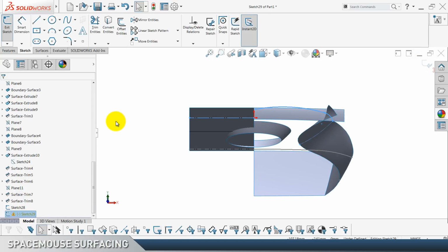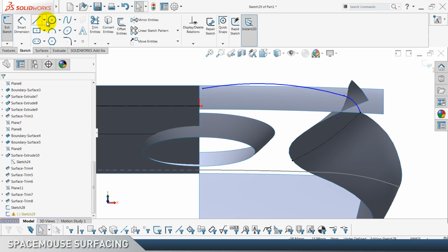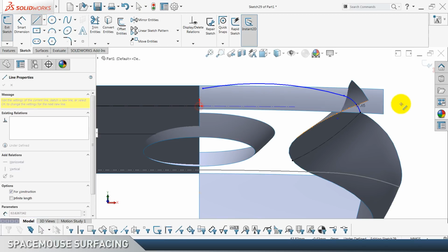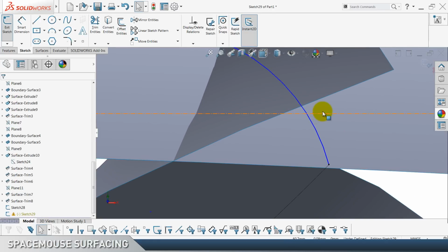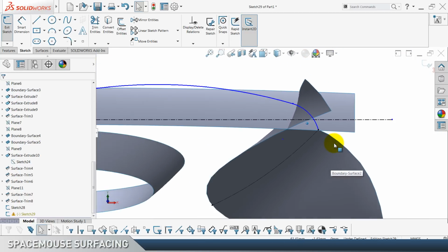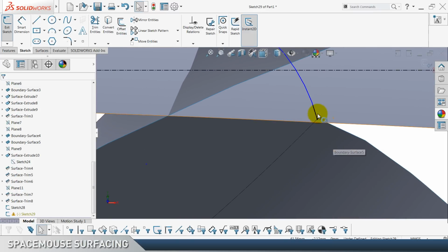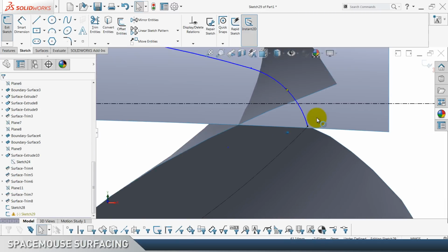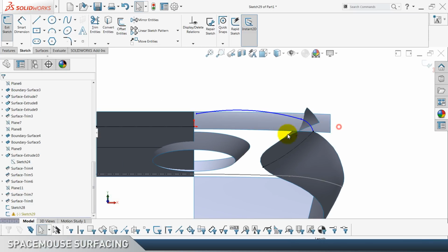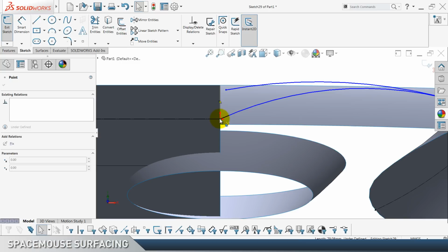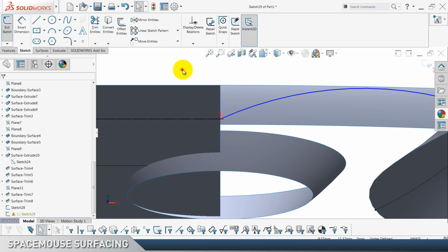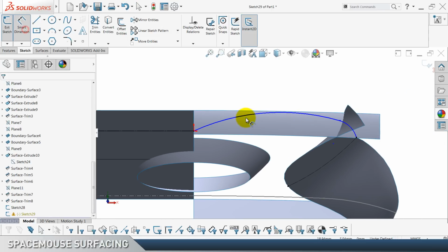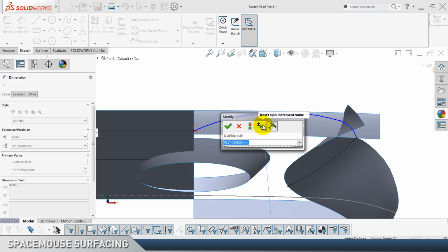So go normal to, and if we now drag one center line like this, let's make it horizontal, you're gonna notice that this height here is what was missing in the previous. When I drew it previously, there was almost no height, and this center line was hitting this point, so that was the problem. Now let's bring back this here, make it tangent. Again, it's trying to screw me over. Now let's actually try adding radius first.